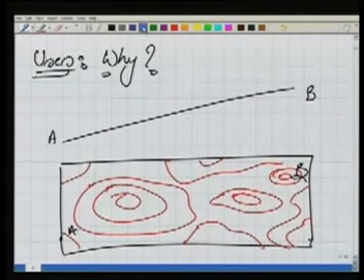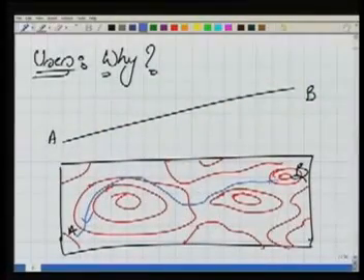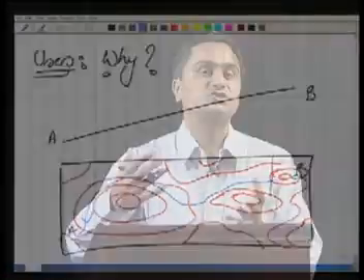Now we are going to take a decision about the road, how the road should be, so that it is optimal in terms of the cost of construction, the cutting, the filling and all these things. So we can design this road here on the map, because on the map we know the three-dimensional structure of the terrain. So this is where we need the contour map.